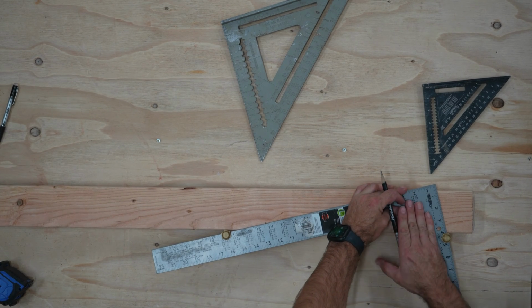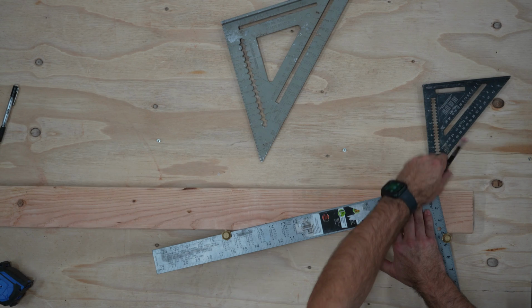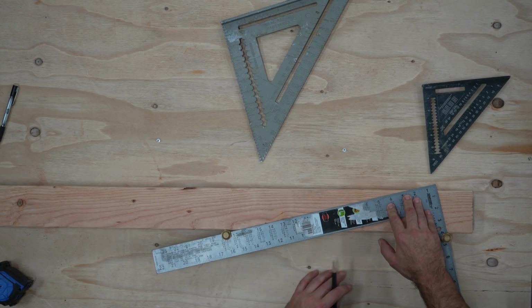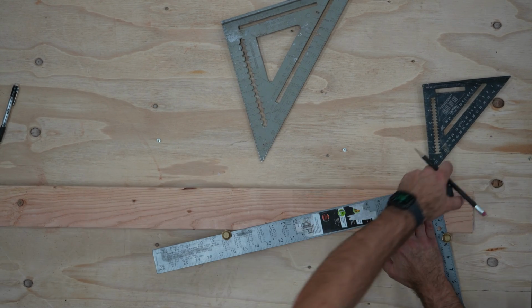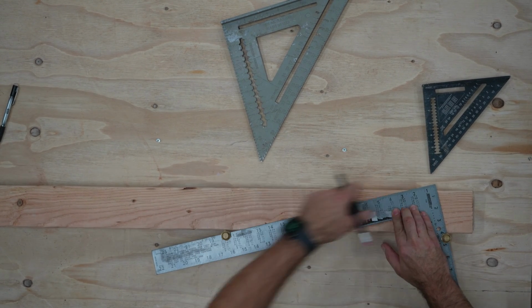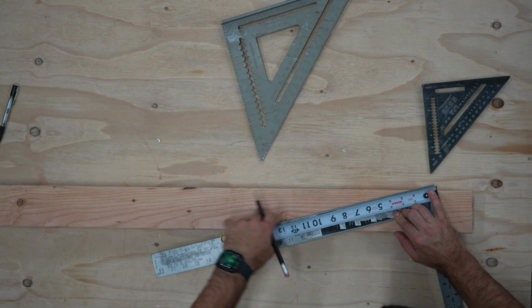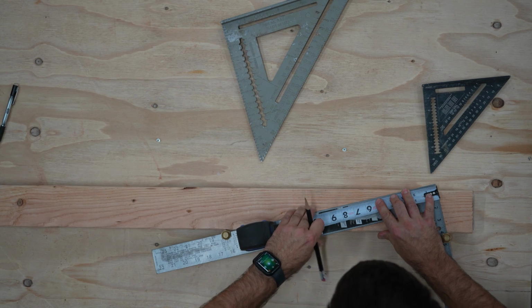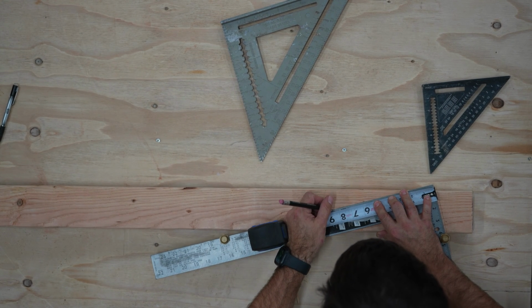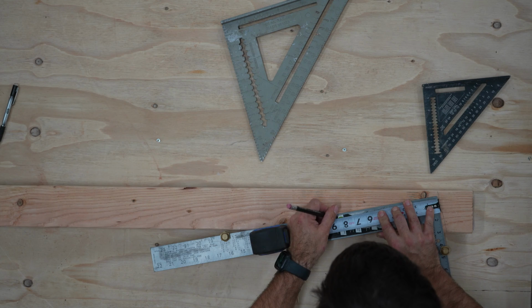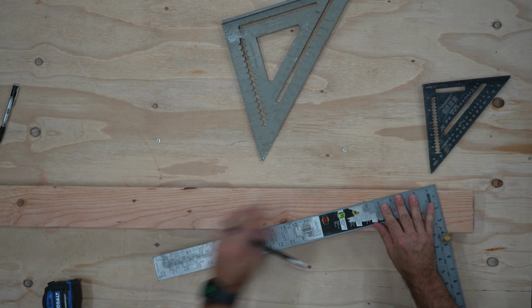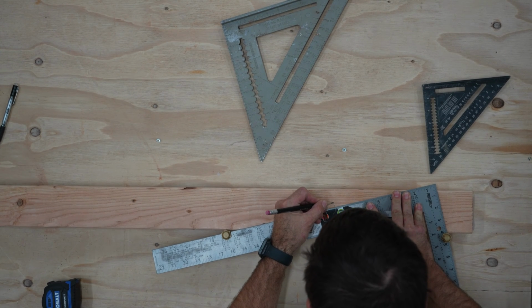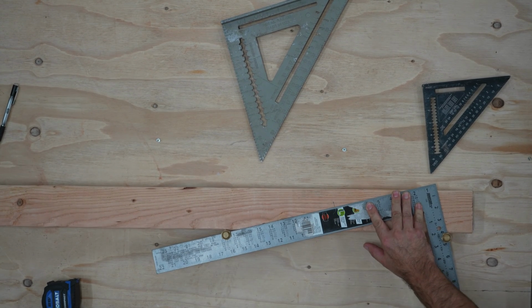To lay out the hip, I want to stay away from the end of the board at least an inch. You'll see why in a bit. The first mark I make is a plumb cut, and it represents the tail end of the rafter. Before moving the framing square over, remember that the blade of the framing square represents the horizontal travel of the hip. So we can make a mark on the framing square at 8.5 inches, and this is where our overhang starts. I'm using my tape measure because the sticker on the framing square covers all the numbers. Then I just slide my framing square over to that mark and make another mark.